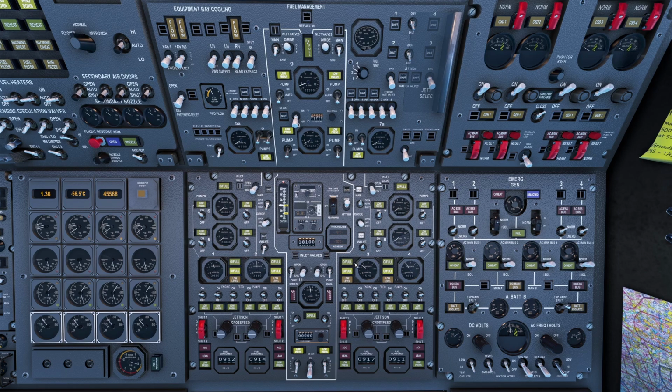Fuel situation on the right is now good. That's alright. We're no longer on low fuel level warning here, so we could actually stop the transfer, but CG is still going forward. As soon as we reach 54, the whole balance CG thing is alright, and we can just stop pumping fuel altogether. I have enough now on the right side. Gonna close these valves and open them up again.